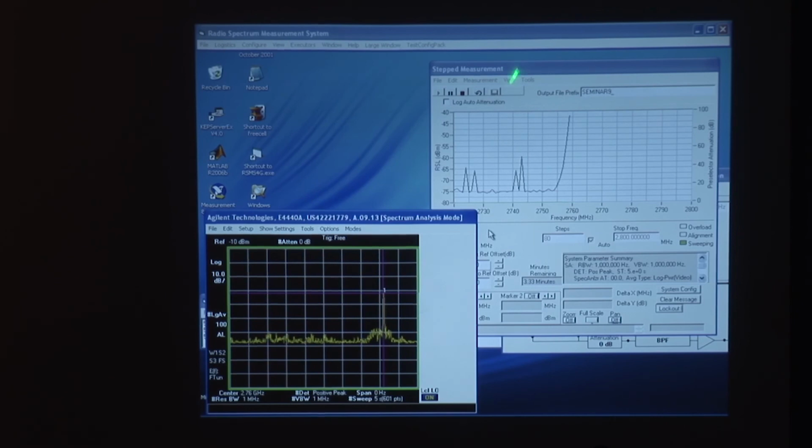The system's automatically adjusting the dynamic range on the display as we get higher level points out of the radar spectrum. Now we're coming down. This is an air traffic control radar that uses a klystron, which is itself filtered with what's called a diplex filter. So it's a very sharp emission spectrum on this radar.